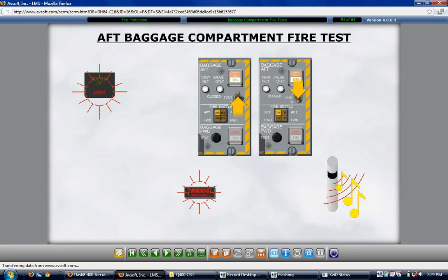If the low rate bottle has lost pressure, indication of the loss is provided during the smoke detector test. The indication is shown by illumination of the low segment on the fire protection panel for the high rate bottle in the baggage compartment not being tested.